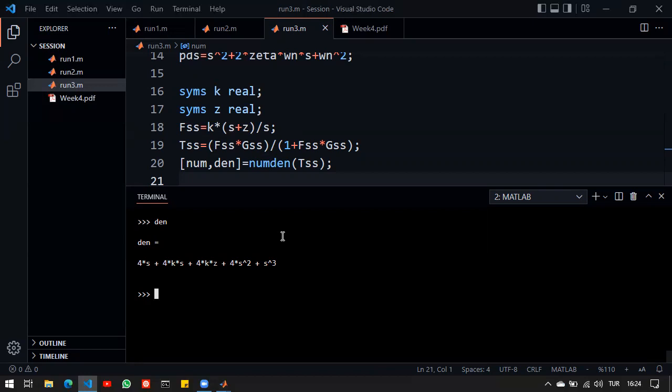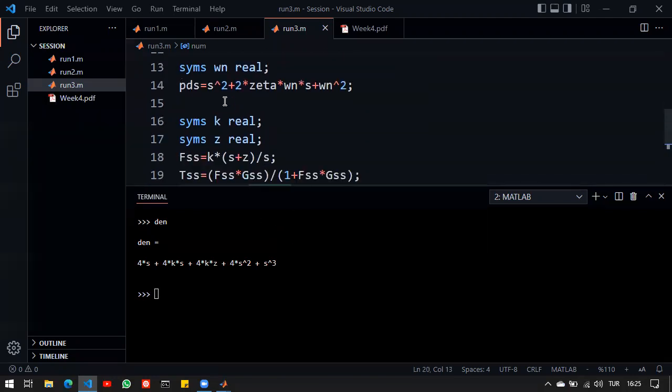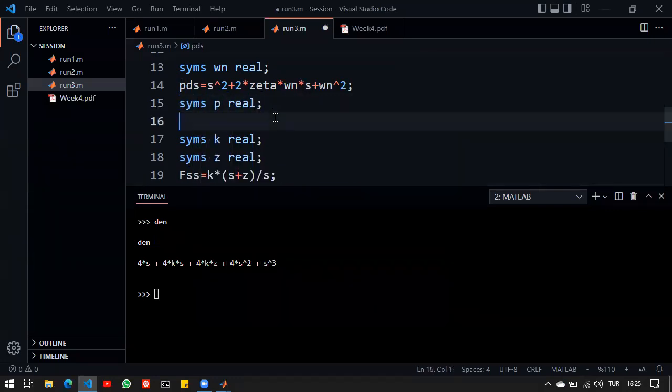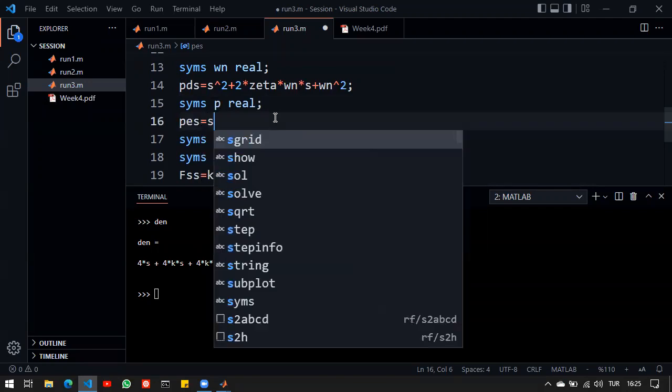because we have to keep one zero and one pole out of the dominant region in order to be able to use the settling time, rise time, overshoot formulas that we have. So this means that during the design of this, I need also to define another pole. And that would be the residue pole here.